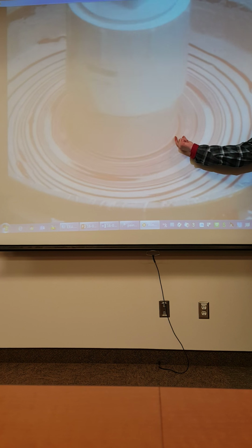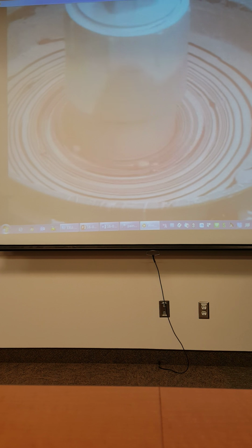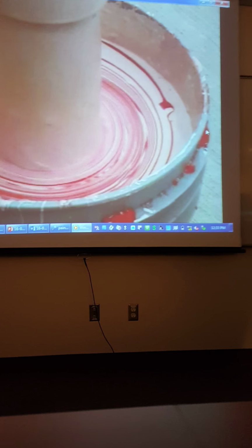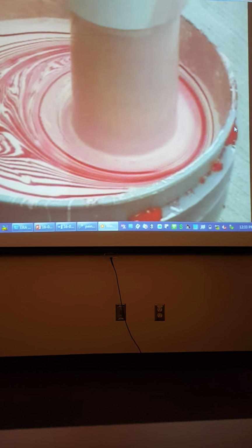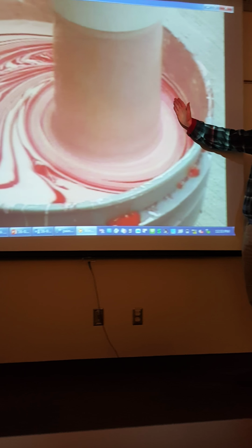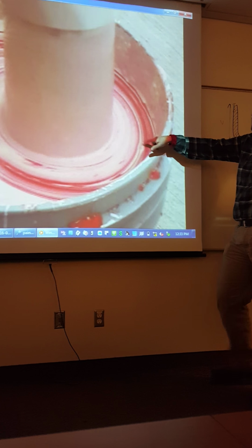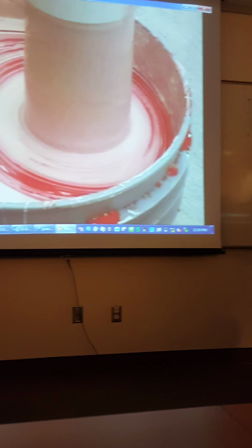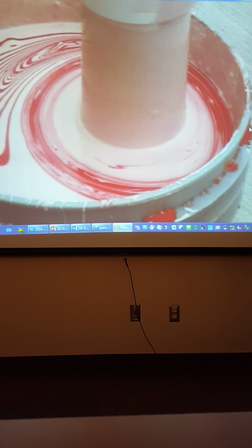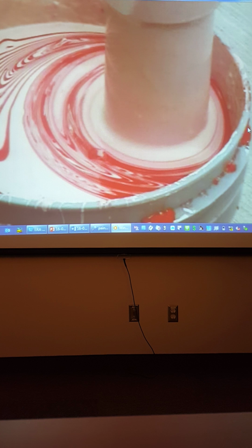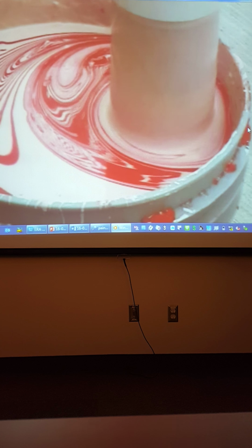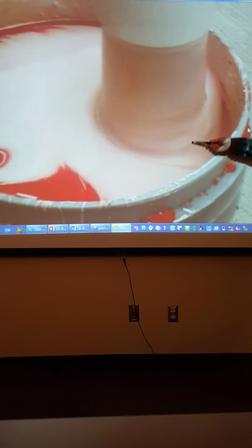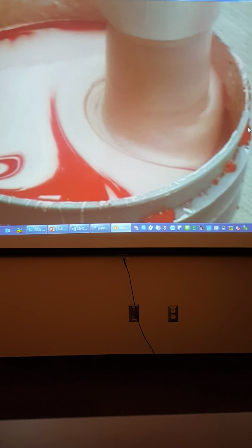Right now it's pretty slow, but you can see the viscous coupling layer. And paint has a similar rheology to mud, a little bit thicker. But in a minute he cranks it up fast and he moves this tube over to the side of the bucket, and you'll start to see some turbulence develop at the edge of the pipe. You say, well, okay, there must be something going on there. That's probably not what it looks like downhole, but it's at least the start of something that would suggest that we've got some different behavior happening when we turn fast enough.